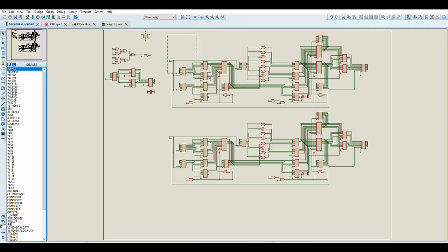The address logic decoding, the tile index read, the flipping logic, the tile address logic selection here, the final tile RAM read, and the output pixel latching logic. Because there's 2, it all happens in less than 333 nanoseconds, comfortably. So that's why we only have 2 here.